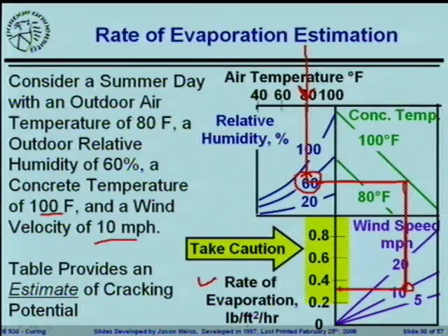Now, one of the things that I will point out is anytime you are in this yellow region, you are encouraged to take caution. That's a big region. Okay, and take caution is kind of one of those things, it's like be safe. You don't really know what you're trying to be safe from. But basically, you want to take steps here to try to minimize the potential for cracking. Obviously, the higher you get, the closer you get to ringing the bell for plastic cracking to occur.